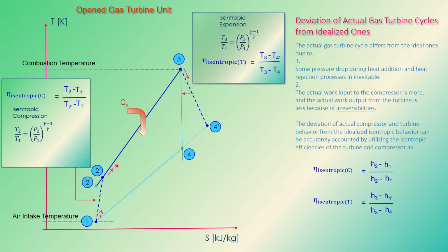So it is known that state point 1 to 2 is your isentropic compression process. In real practice, there is no perfect isentropic process, meaning no perfect absence of heat loss, no perfect absence of energy loss due to heat to the surrounding or internally. In real life, you have a certain amount of energy loss and it becomes irreversible.